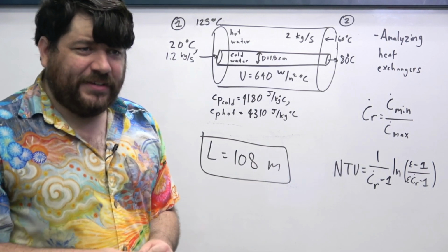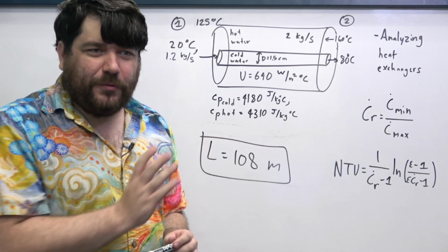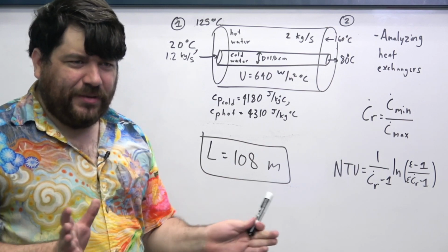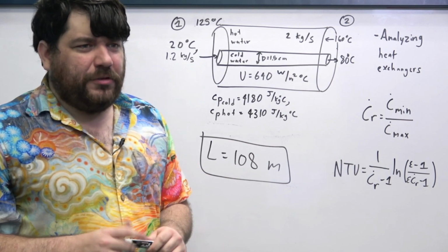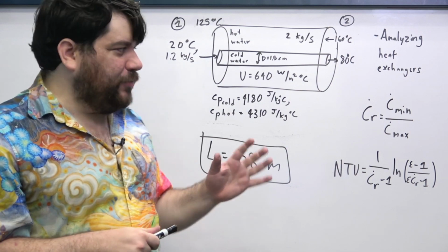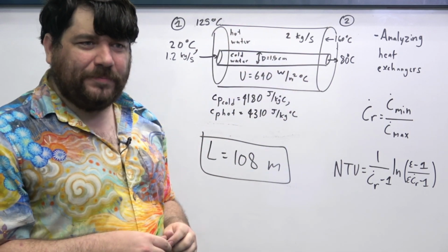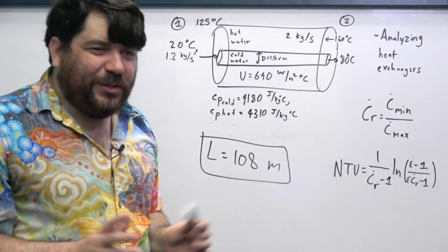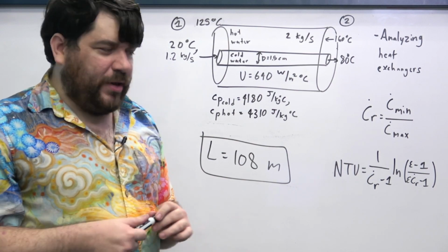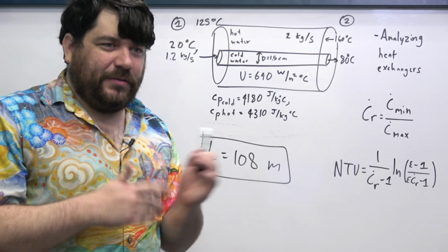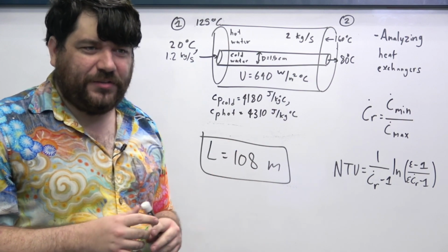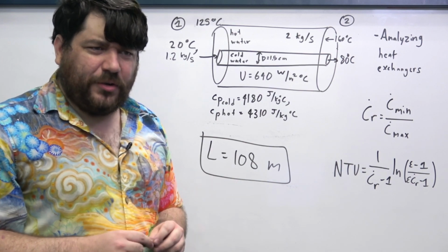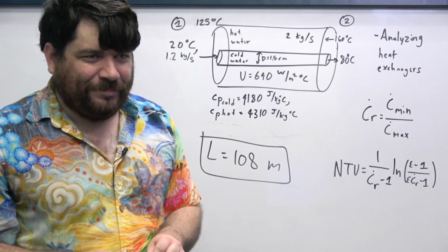And so you can see that, assuming that we have enough information, there's two different ways to go about heat exchanger problems. We can either rely on correlations that connect dimensionless quantities inside of them, which we will often have to do whenever we don't have the ability to set up a problem in the diagrammatic way that I did just now, or we can use the delta TLM method, where we calculate a log mean temperature difference, and then we relate the heat transfer rate through the heat exchanger to the overall heat transfer coefficient and the surface area and that sort of thing.